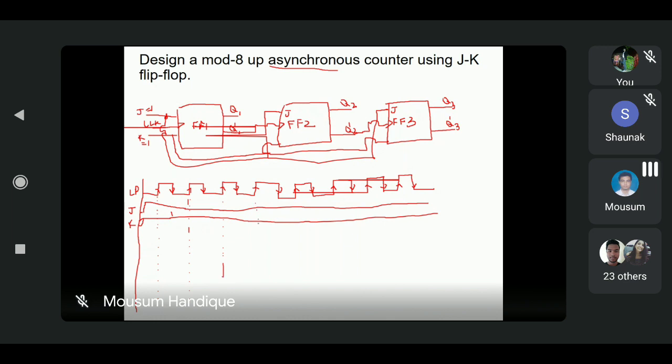Okay. Now see here, Q1. Suppose we are using Q1. Q1 means this one is the Q1, Q2. Because if we know the Q1, then automatically we know what Q1 dash is. If Q1 is 1, then Q1 dash is 0. It is the complement form. So when the first clock pulse occurs, what is the value of Q1? That means the timing behaves this way.